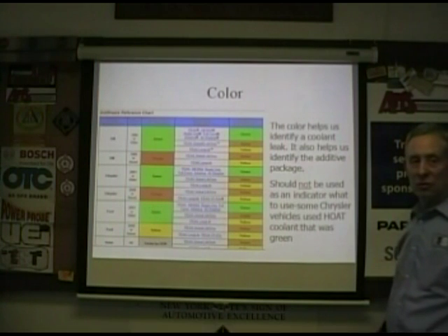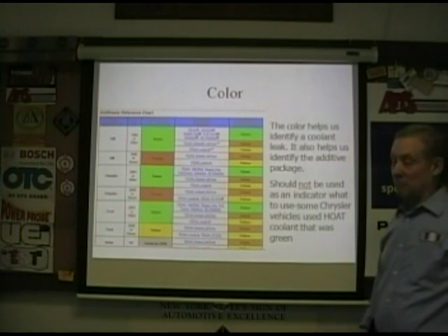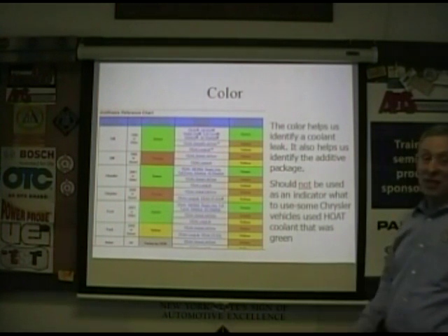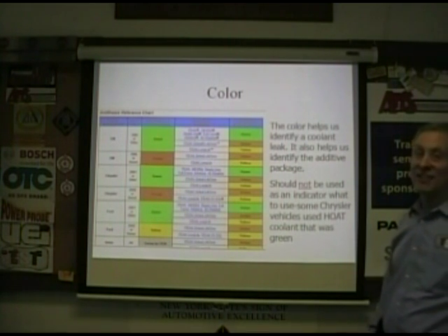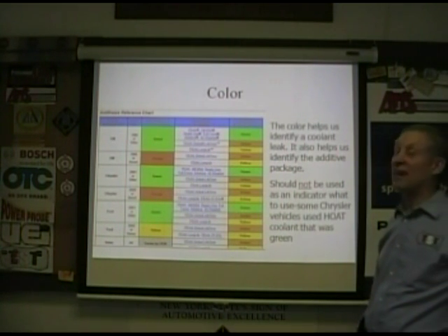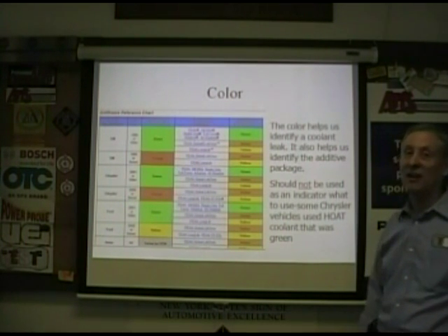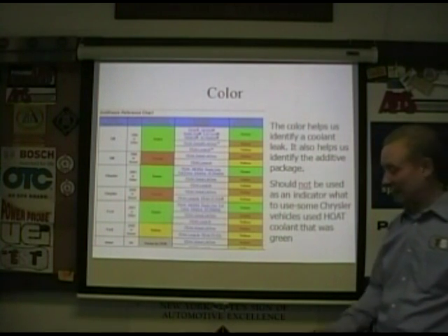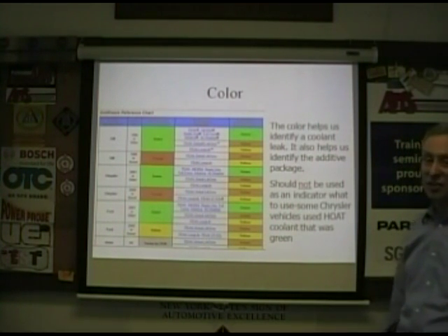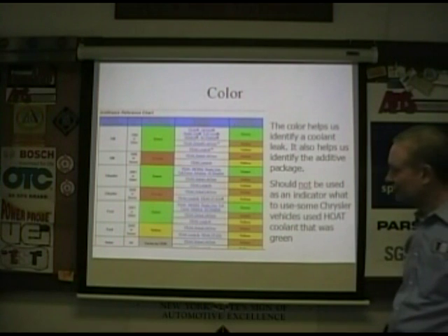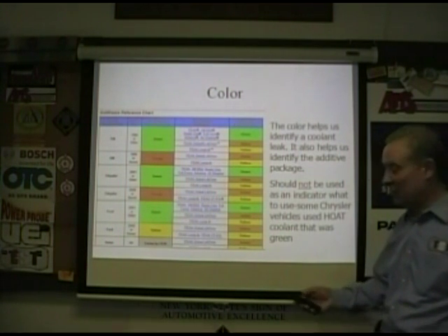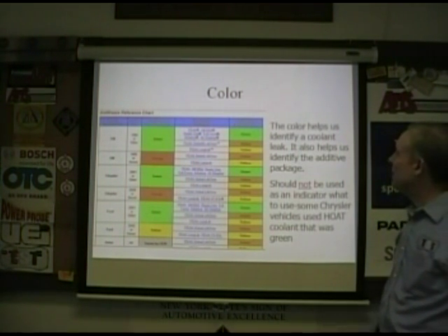So Pierre, you can use like a black light type thing, like an air conditioner? Most, yes, absolutely. It's not exactly the same frequencies as air conditioning necessarily, but most manufacturers of antifreeze or coolants today put some type of UV dye in the coolant so you can see it. You got to watch that your glasses are matched to your light. There are different frequencies of black lights, but it is possible to do it.